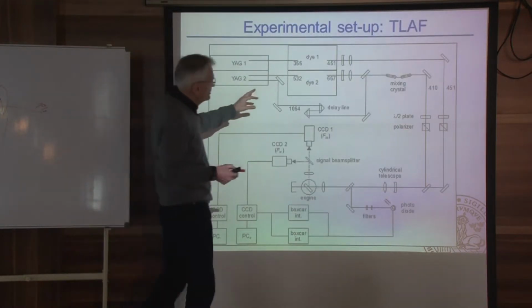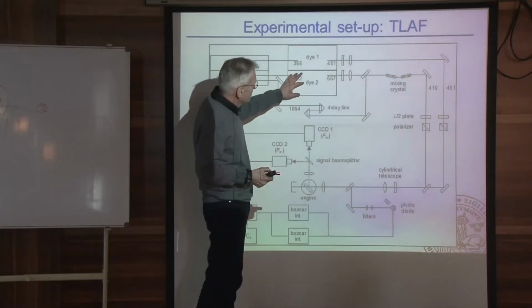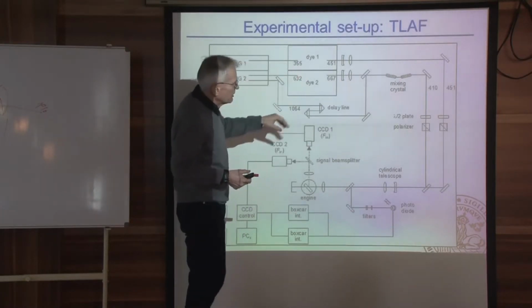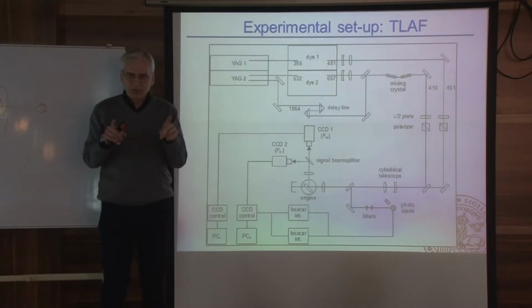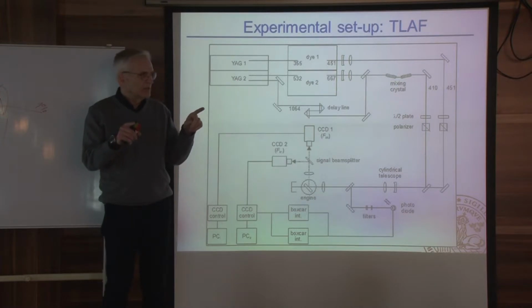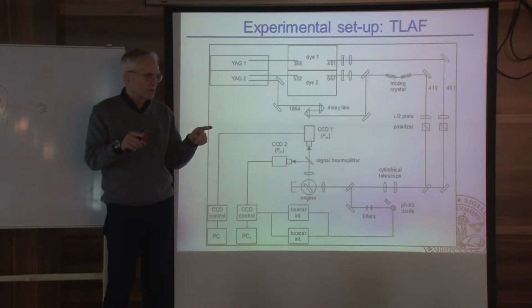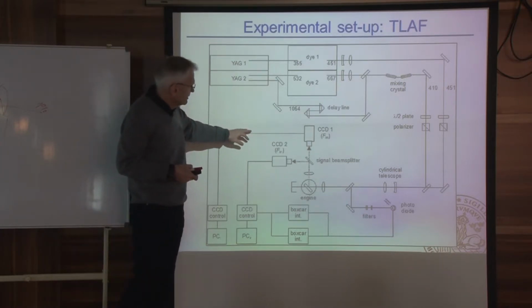Then I haven't gone into detail previously, but it's also possible to measure temperature. If you choose two specific wavelengths in the molecular or atomic species of interest, you can probe the Boltzmann distribution. And that's what we have done here in this engine.